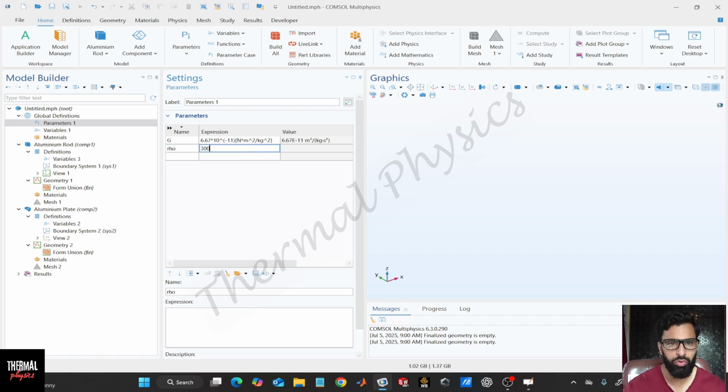Say we give 300 as the density. We start a square bracket as already said, then kilogram per meter to the power of this, then cube, and close the square bracket. Now we have defined 300 kilograms per meter cube. Then we use another term, velocity v. Suppose we give its value as 5 meters per second. So we have 5 meters per second here.